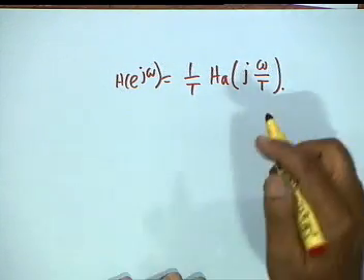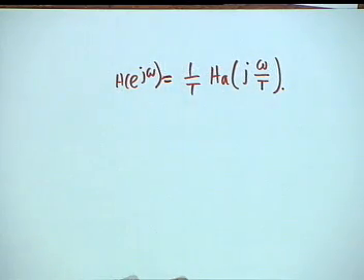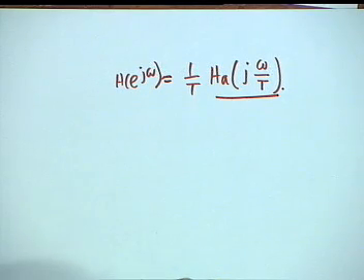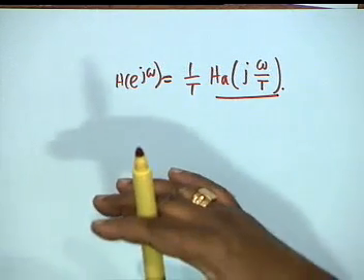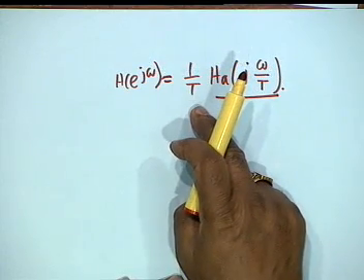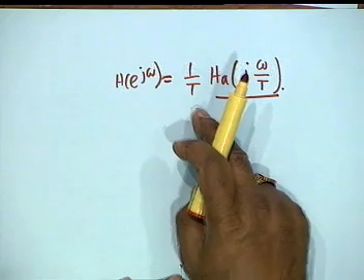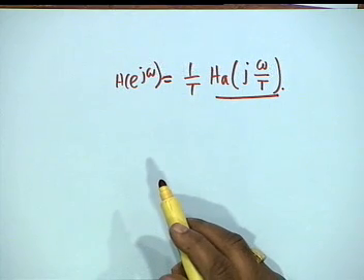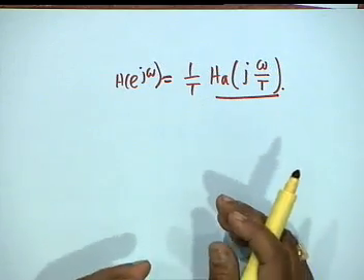Even if the original spectrum was band limited and sampling was done according to the sampling theorem, when capital T is small, that is for a high sampling rate, even if capital H A j omega is normalized, normalized means the maximum amplitude cannot exceed unity, maximum amplitude is 1. The maximum amplitude of the digital filter transfer function shall be very large when capital T is very small. That means that there shall be definitely problems of overflow. Agreed? We cannot allow this signal to grow indefinitely.